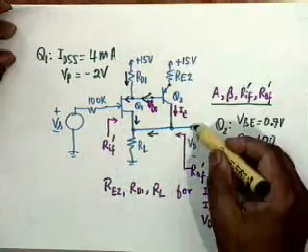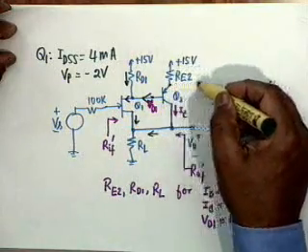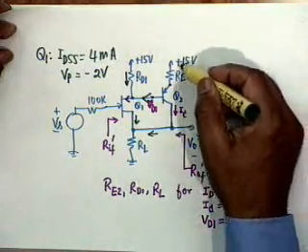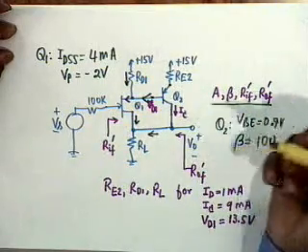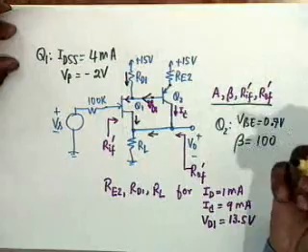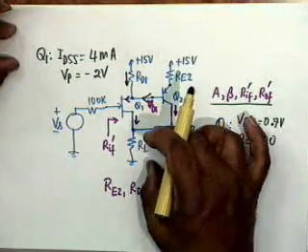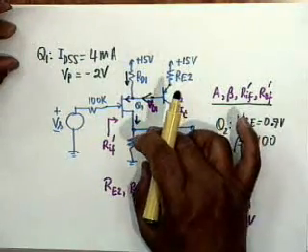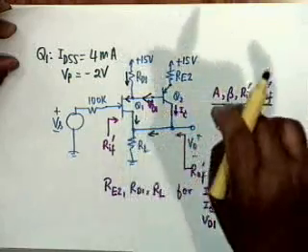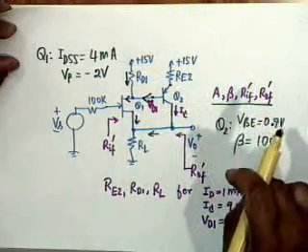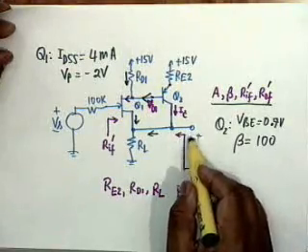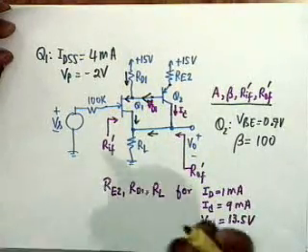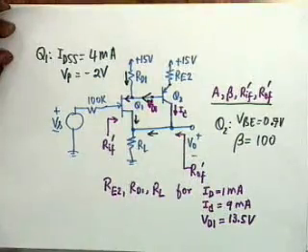If the output voltage was being taken here, then it would have been a series connection here. It's not a question of R pi, where it is connected. The feedback voltage, VF, is it proportional to the current through the load or the voltage across the load? It is obviously exactly equal to V0, and therefore there can be no question. It is a shunt connection.